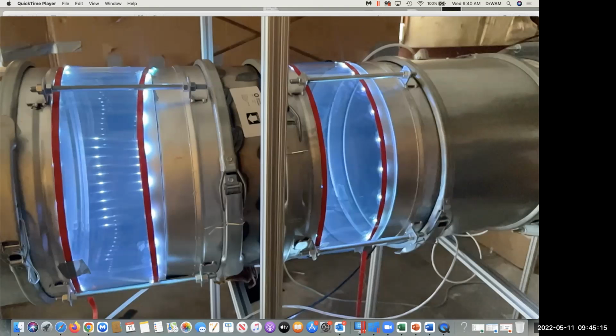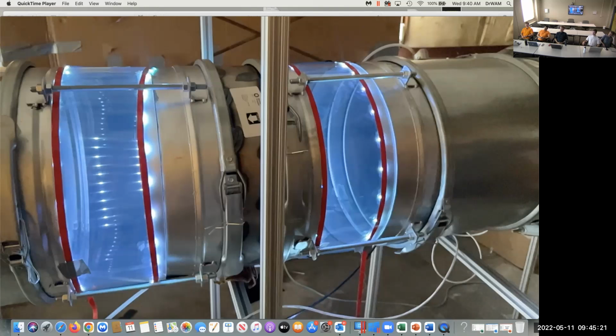Just a thought. Well, I think I can handle that one. That was my first thought: let's put it on the supply side where it really mixes. That's from the return side where it really mixes good. And that's where Blender Products would put their device, where they're bringing in the outdoor air that is mixed with the return air. What he wants to use that blender for is to get a good bulk temperature across the section of the duct, a well-mixed airflow.